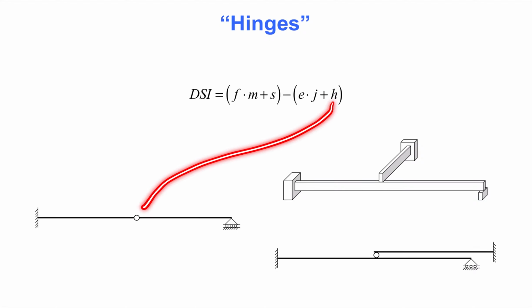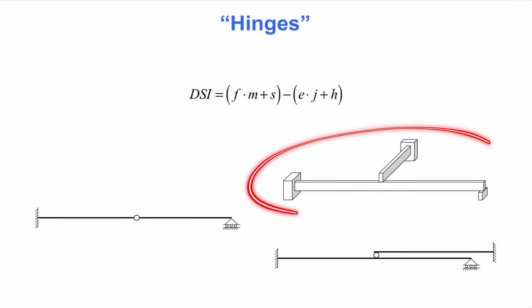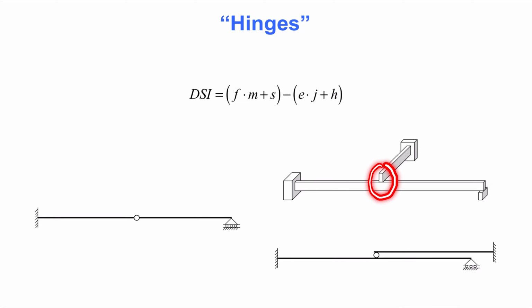The example structures on the right-hand side will show that H can be a bit more complicated. Specifically, look at the joint where the upper beam is resting on the lower beam. This is a 3-dimensional structure, so there are 6 unknown internal forces in each member. At this joint, we must ask which of those 6 forces transfer from the upper beam to the lower beam.